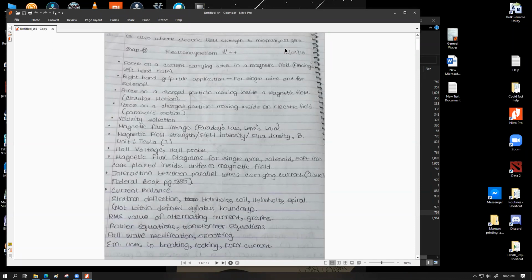Iron can show two types of magnetic behavior. One is the soft magnetic behavior, and the other is the hard magnetic behavior. Soft magnetic behavior is such that it becomes magnetized very easily. It would normally be demagnetized. Naturally, it would show no magnetic behavior at all. So it would be naturally of zero magnetism, but it can be magnetized very easily under the influence of a magnetic field or another magnet, and it can be demagnetized very easily as well.